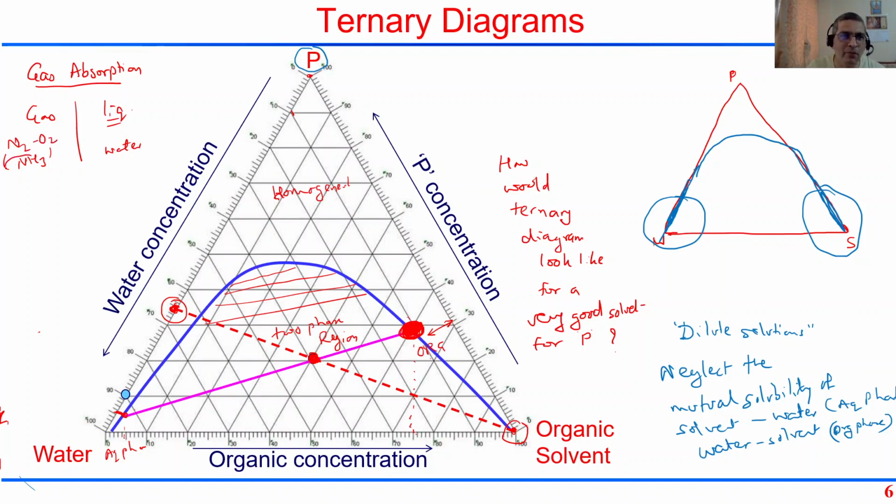We only considered ammonia solubility in water. We did not consider vapor pressure of water in the air phase, gas phase, nor did we look at the solubility of nitrogen and oxygen in the water phase, isn't it? So we could treat it as if there is only one solute, ammonia in this particular case, that is at equilibrium between the gas and the liquid.